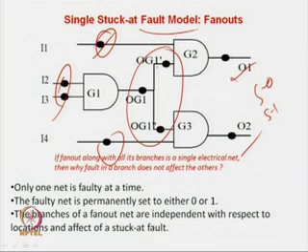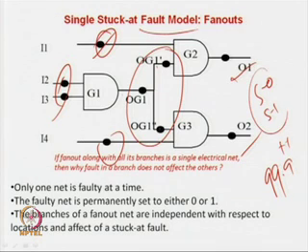So, now we are doing structural testing, but this is not at a functional level. And it has been shown that if you can do this, then the test coverage is as high as 99% accuracy. In a few lectures down the line we will see how this structural testing with this fault model will help to reduce the number of registers, number of pins, and everything will be very neat. But for the time being, take it from my side that if you test a circuit forgetting about the functionality of the AND gates and just verify that these nets do not have stuck at 0 and stuck at 1 faults, still the coverage is as high as 99.9% plus.